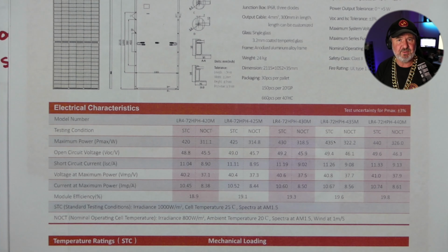So you increase the irradiance, you increase the current. So it's not unusual to see 10% more irradiance under the right conditions. I've measured over 1,100 watts per square metre here on my pyranometer at the Smart Energy Lab. And so those sort of conditions mean you get another 10% of current. So hence our overload factor of 1.25 times.